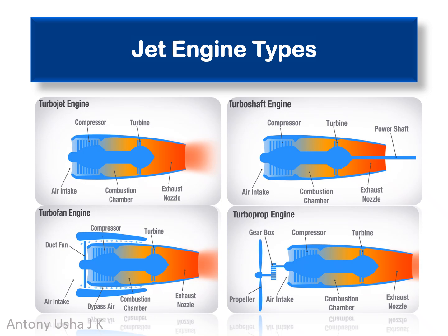The turboshaft engine is commonly found in helicopters and some naval vessels. Similar in core design to a turbojet, the turboshaft redirects most of its energy not into producing thrust but into driving a power shaft connected to a rotor or gearbox. The exhaust still exits through the nozzle, but the thrust is minimal compared to the shaft output. This makes the turboshaft ideal for mechanical power delivery rather than propulsion.